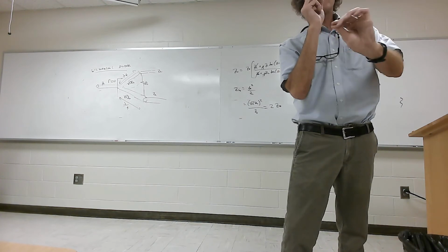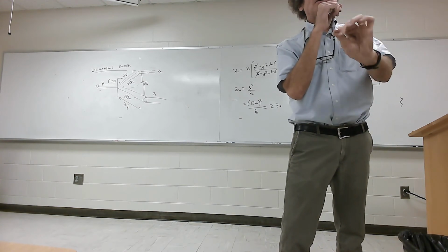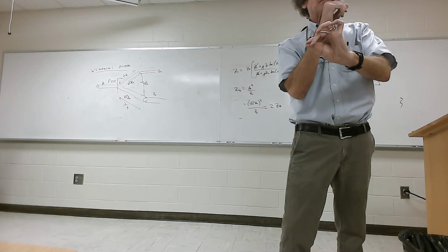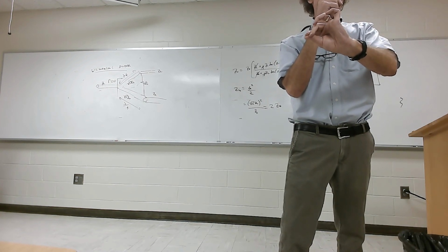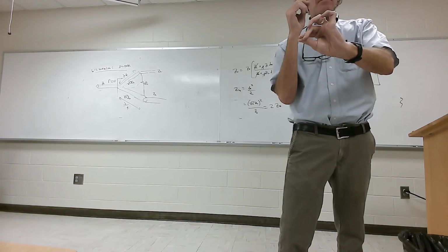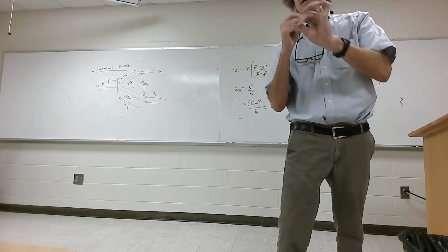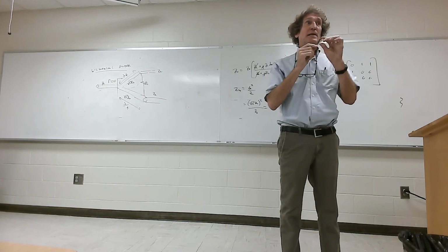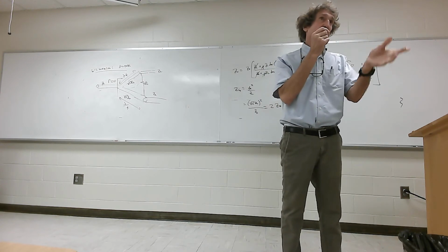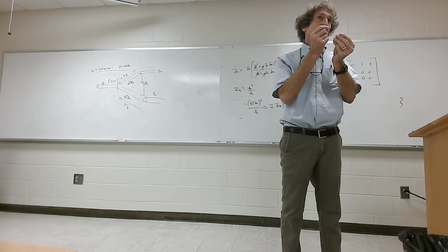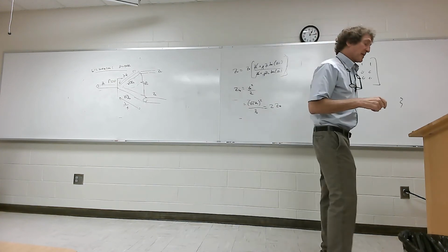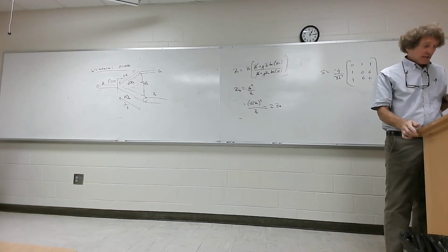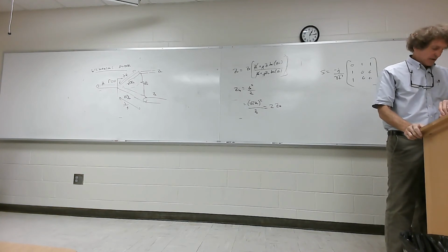Then they'll have one last port, which usually doesn't do a thing, but sometimes they'll have like 70 dB loss and use it as a secondary, very low-level signal for something else. Basically they're bleeding off signal strength, reducing it, just so they can catalog information. That has nothing to do with a circulator. But that's really a 4-port in a nutshell, and I'm not even going to cover that today.